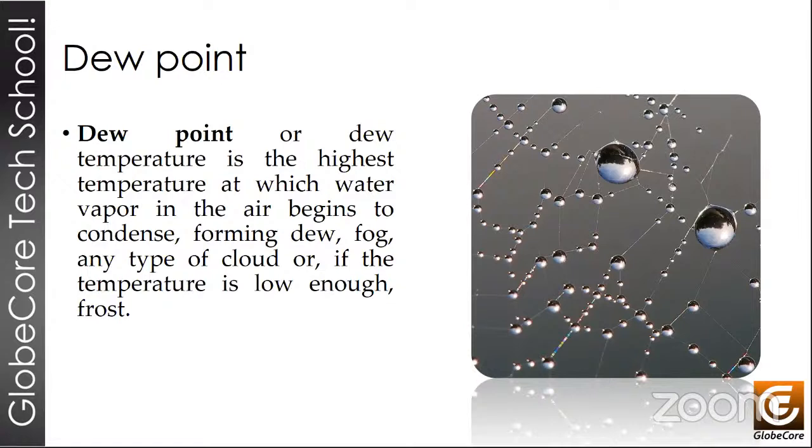At present, enough experience has been accumulated to assert that this method for determining moisture content is correct and does offer sufficient accuracy. In general, the procedure is to fill the transformer with dry gas, which can be air or nitrogen, in such a way that after a certain time, during which the state of equilibrium and humidity is reached, the dew point of the gas is measured, and this value helps us determine the residual moisture in the transformer insulation. Next slide, please.